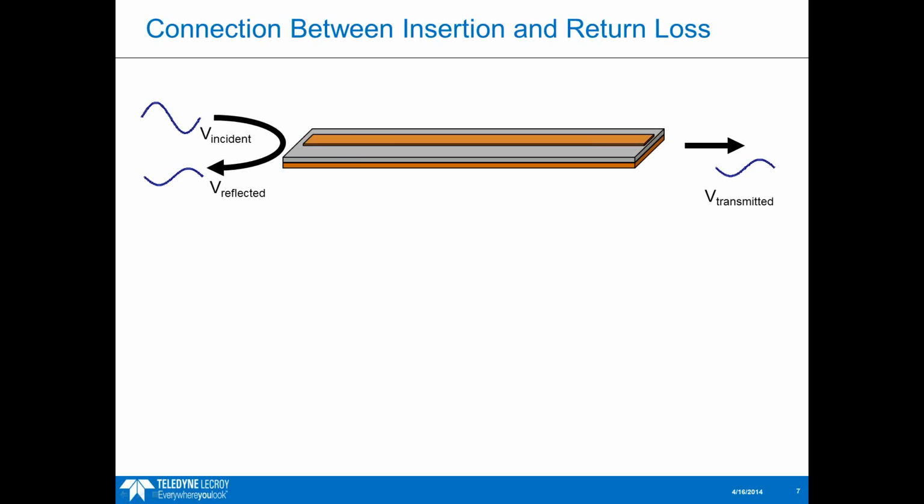It also depends on how much loss. If it's a really lossy interconnect that's 20 meters long, you're going to be in trouble. There are also specially designed instruments out there for measuring really long things, like cable testers that are meant for measuring things which might be 1,000 meters long, for example.